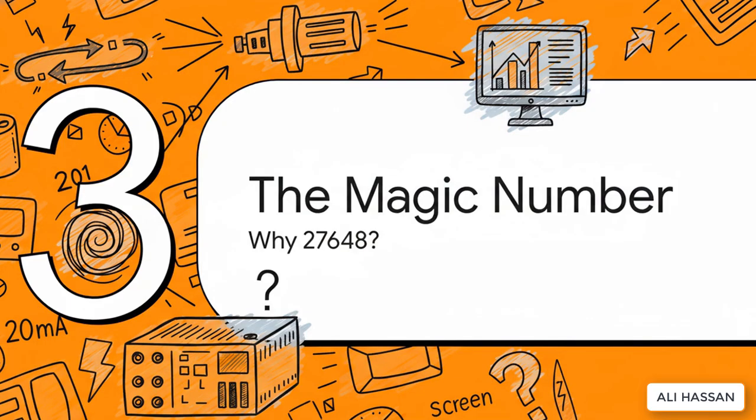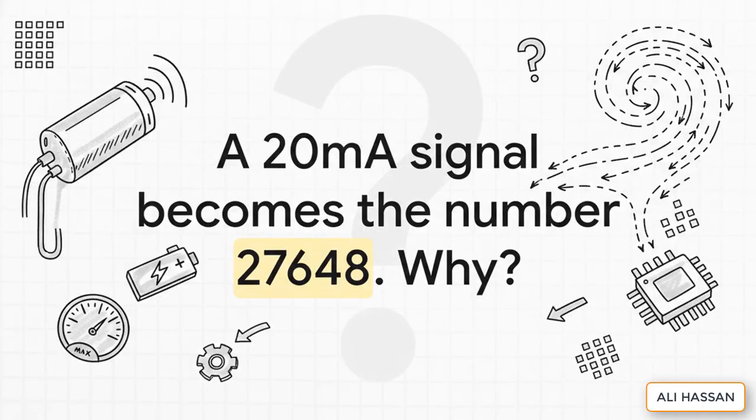But here's the thing, it's not just any number. When our sensor is maxed out, sending that full 20 milliamps, the PLC doesn't see 100 or full, no. It sees a very specific and, let's be honest, kind of strange number. So let's dig in and find out why. The magic number is 27,648, a full tank, maximum pressure, 20 milliamps of current.